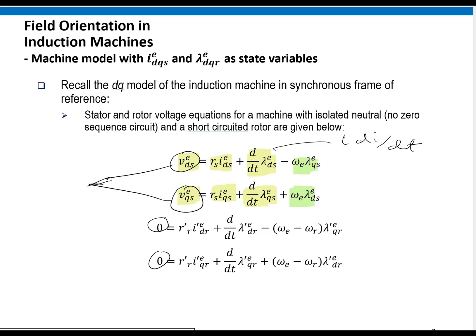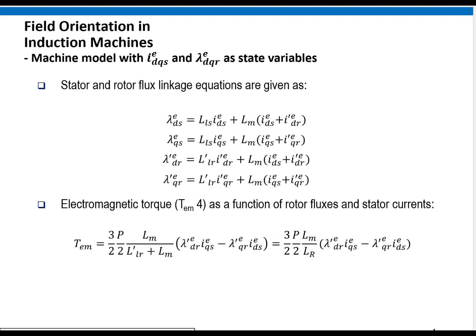And this is really coming from the output of your PWM controls. That's the switched voltages applied that are going to drive controllable variables within this. You've also got different stator and rotor flux linkages here. So we had the stator flux linkage proportional to this D-axis current. I'm thinking this is more torque related, so I'm going to use this blue. That's your torque Q-axis flux linkage. And you can also come up with rotor winding flux linkage terms as well in the D and in the Q here.